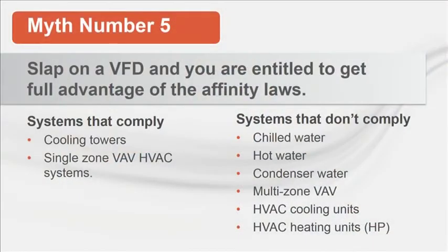So while the affinity laws do predict the ideal performance of dynamic compression devices in frictional flow loss systems, there are many more HVAC systems that don't comply with these operating principles. A non-compliant system is any one that has a control valve, fixed static lift, a pressure control set point, a required minimum flow, or back pressure in the system.